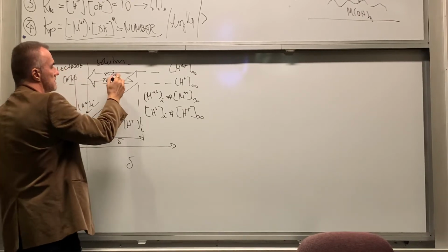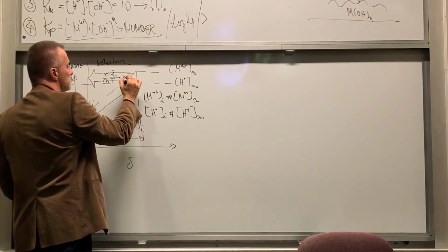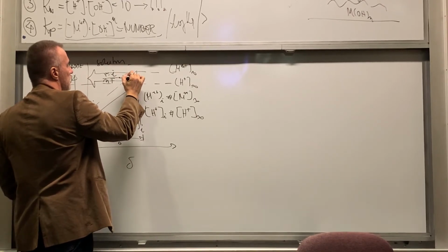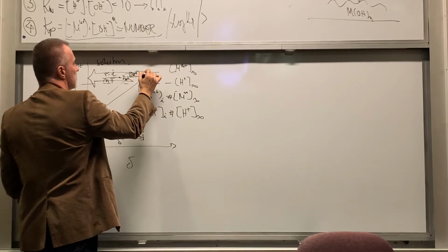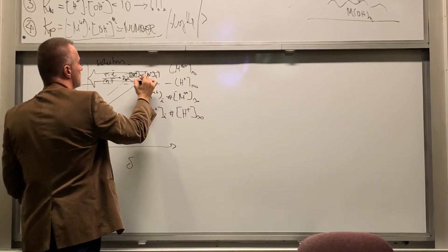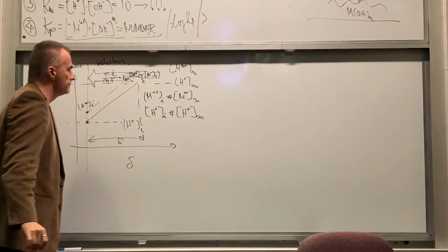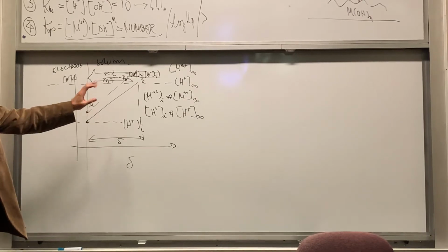That's equal to flux, and we know that this is equal to D metal ions diffusivity times Mn plus bulk minus Mn plus at interface divided by delta, right? That's something we already covered if you look back.